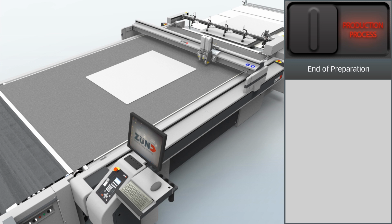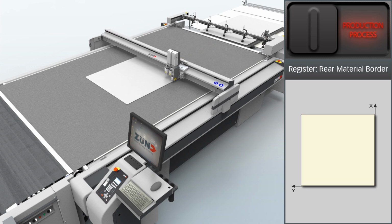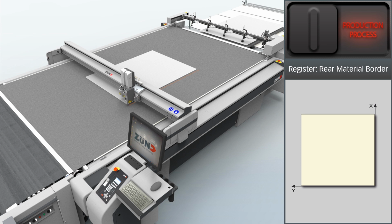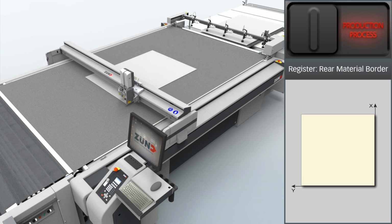So for the rest of the production process, all further panels are positioned on the stack with the printed side facing downwards. Register the material border of the turned panel on all following panels. In our example, the next processing steps are through cut and crease.